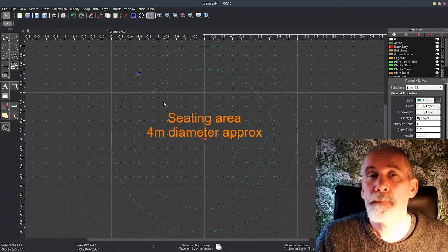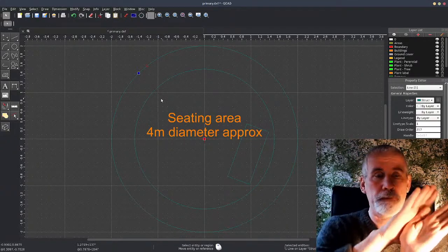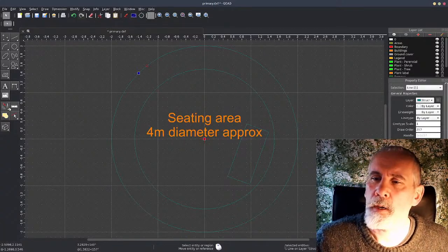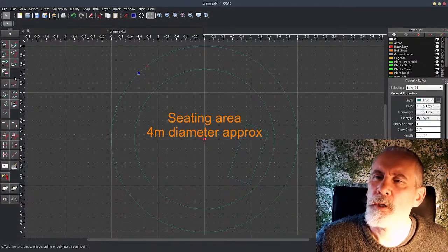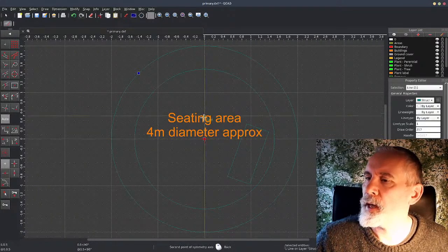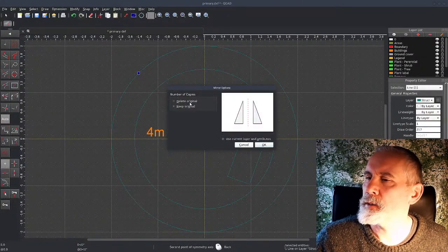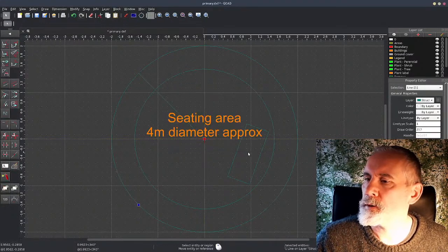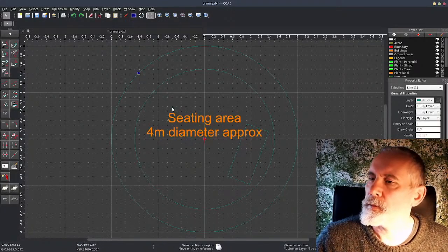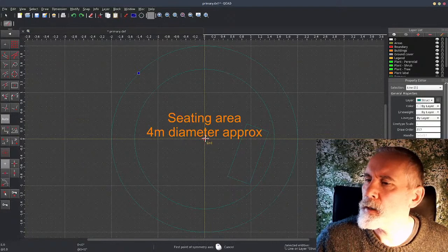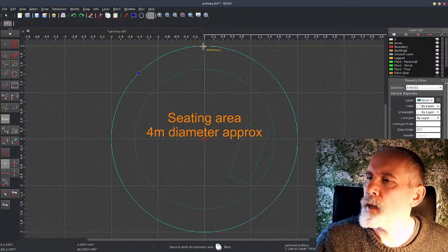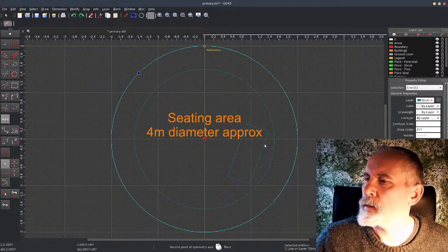And I want to use the mirror tool. I'm going to mirror that line and flip it over so it goes to the other side. So I get to the modification tools, and this one here is the mirror tool, and I'll mirror it, and keep the original and mirror it over. Oops, wrong way. Oh, sorry, that one. Mirror, up there, and then keep original.